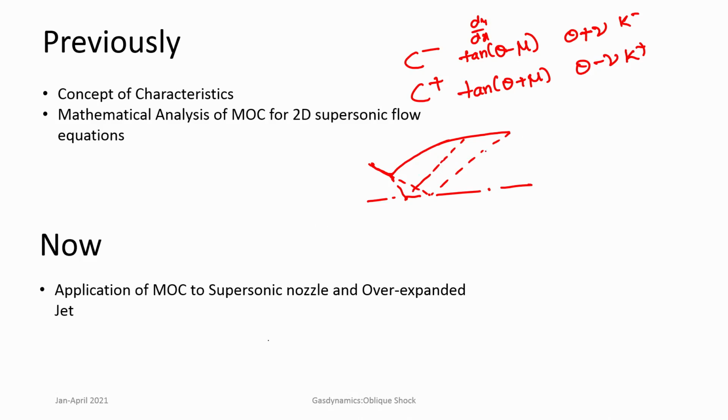So that is the principle that we are going to use to look at how to design such nozzles. We had a relationship for what the flow turn should be. Now I know my exit Mach number, M_E, is known.